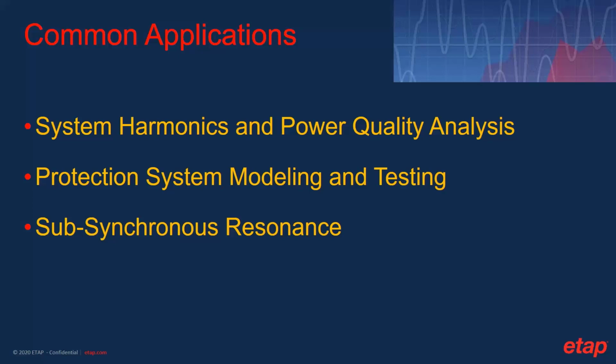Subsynchronous resonance, the torsional interaction of thermal generator shafts, like interactions that occur at frequencies below 50 Hertz or below 60 Hertz, are termed subsynchronous oscillations. Again, those oscillations cannot be studied on RMS and people have to use EMT type programs. So those are some of the common applications, and towards the end of this presentation, I will show some simulation examples to highlight, like I said, data requirements and the type of results that you can observe through EMT simulations.